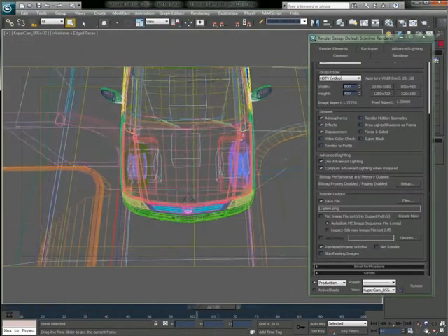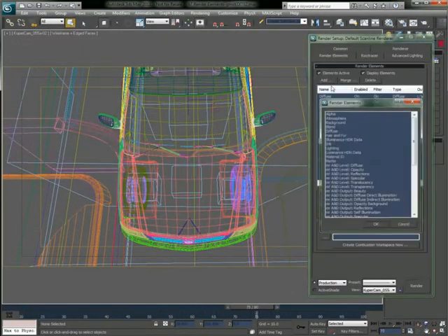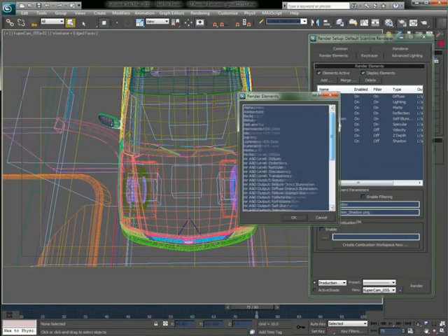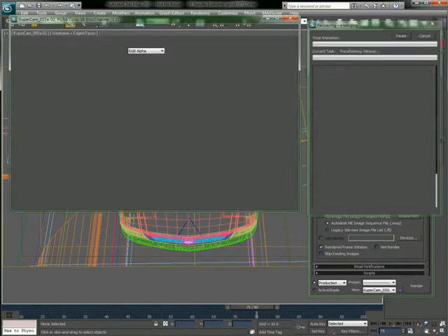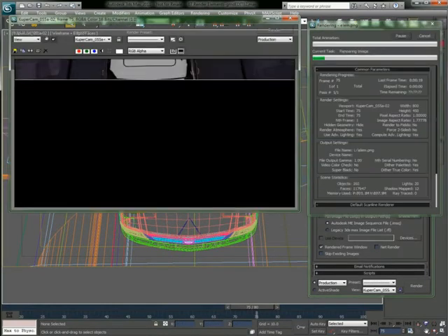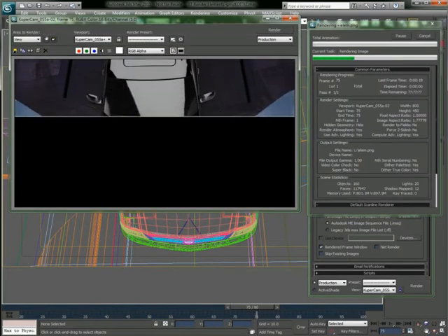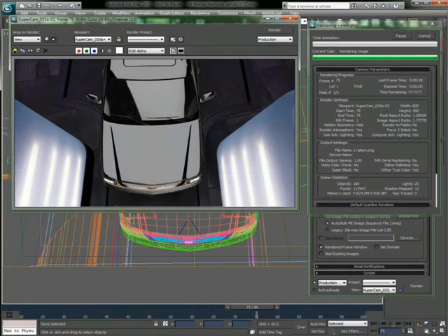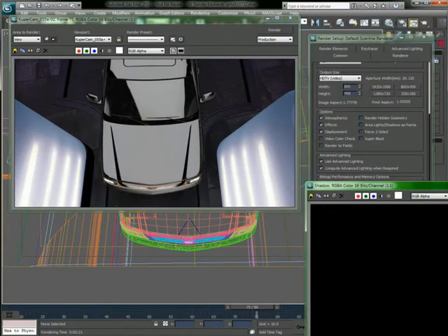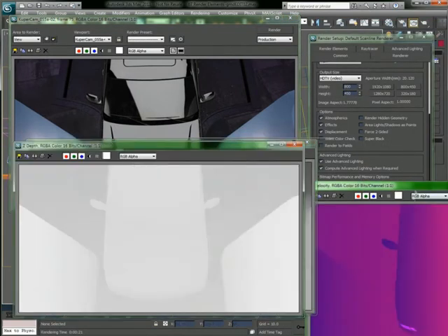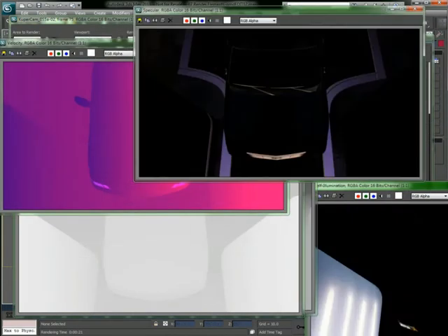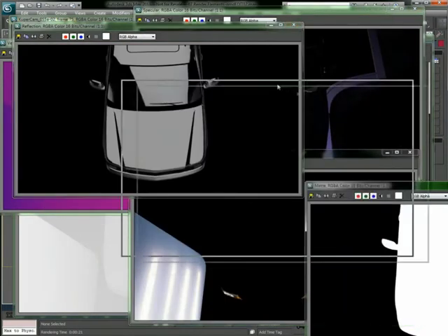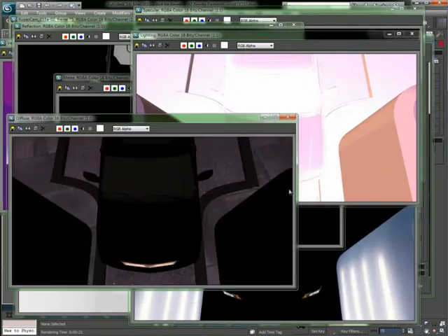Another powerful feature that facilitates many different post-production requirements is the Render Elements dialog found in 3ds Max. In addition to outputting a straight image from the various renderers available, the Render Elements dialog allows users to optionally separate key render passes or layers upon output. Several common options include specular, diffuse, shadows, direct and indirect illumination, and matte render elements.